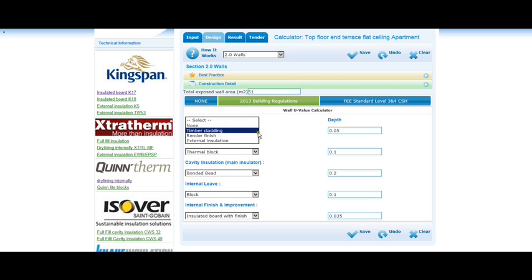The designer chooses the structural materials and insulation materials to be used, and the software calculates the appropriate depths of the insulation material. The Foresight software knows that the recommended U values needed to achieve FEE standard are not enough in this particular case, so it will present better U values to compensate for the bad Y factor calculation.